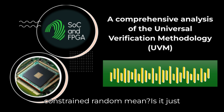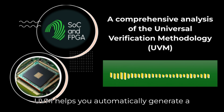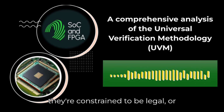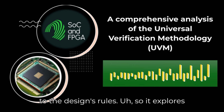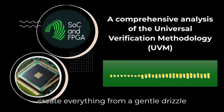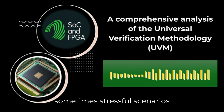So what does constrained random mean? Is it just throwing random data at the chip? Not quite random chaos. It's smart random. UVM helps you automatically generate a vast number, potentially billions, of test stimuli, inputs for your design. But they're constrained to be legal or perhaps strategically illegal according to the design's rules. Ah, so it explores possibilities but within boundaries. Exactly. Think of it like a highly intelligent storm generator. It can create everything from a gentle drizzle to a Category 5 hurricane, but it always obeys the laws of physics. It generates interesting, valid, and sometimes stressful scenarios automatically.